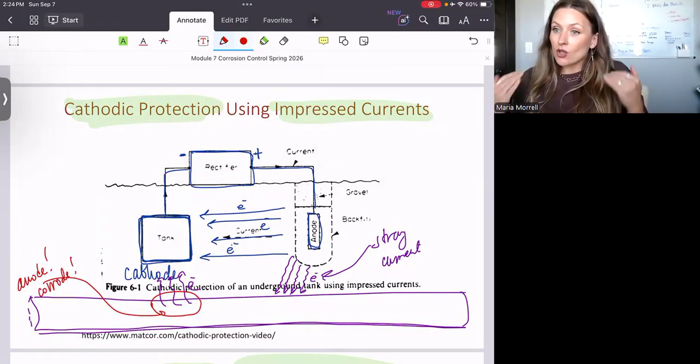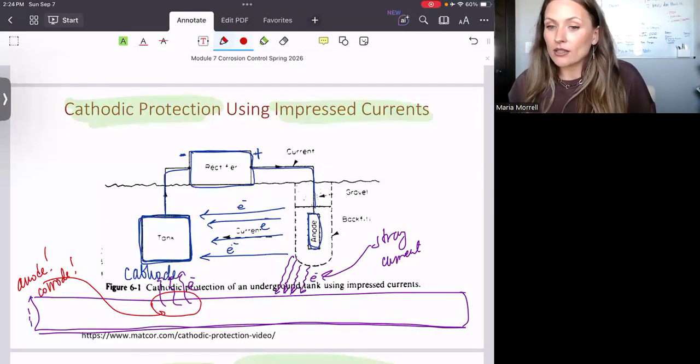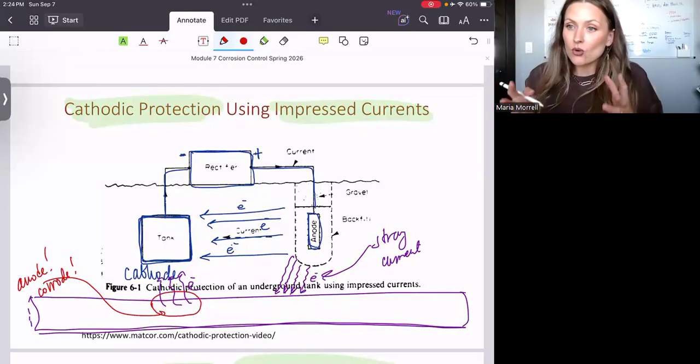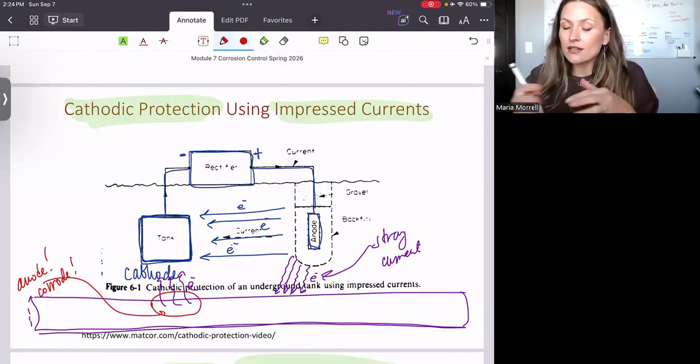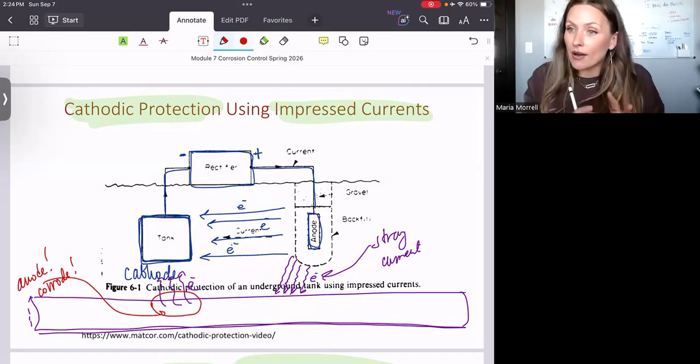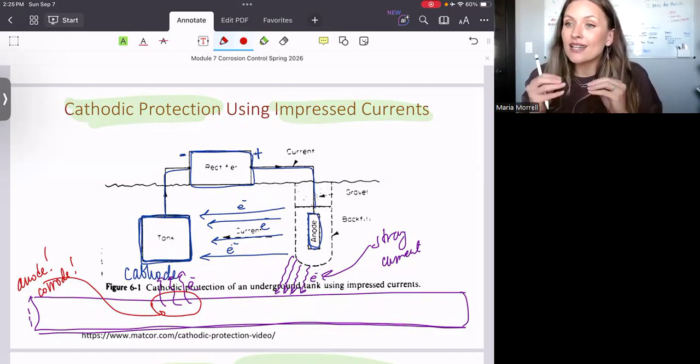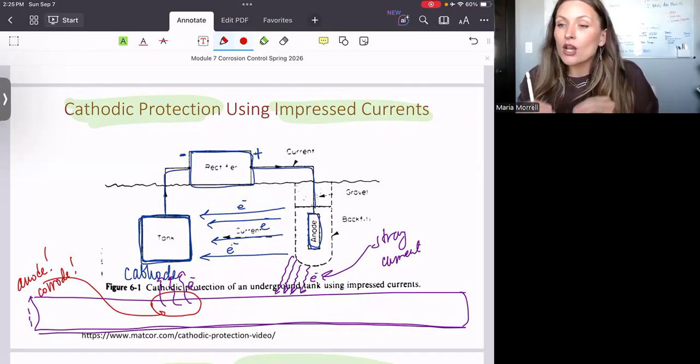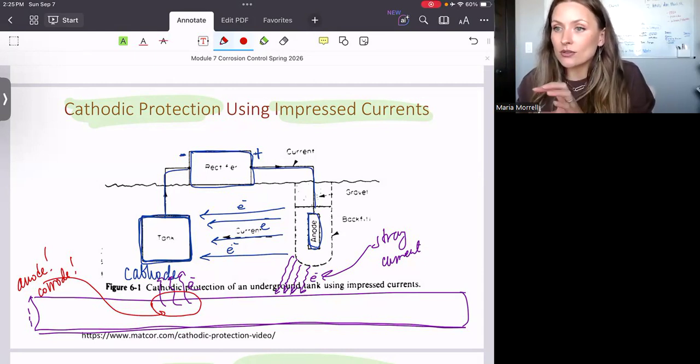And without knowing about that pipe, if we had known about that pipe, we would have chosen a different position for my tank, a different placement. We would have put some insulation. We would have taken into consideration the knowledge of the possible stray current. But let's say in the scenario where we didn't know that, his pipe is going to slowly and steadily corrode due to the system that I installed, due to the stray current.